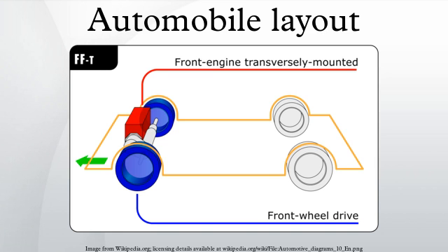Unusual 4WD layouts. From 1989 onwards, some models of Porsche 911 feature a rear-engine 4WD layout, which is akin to a longitudinal front-engine 4WD layout installed backwards with the engine at the rear of the car. From 2007 onwards, the Nissan GTR features a front-engine 4WD longitudinal layout, but with the gearbox at the rear of the vehicle. This provides a more ideal weight balance, and improves directional stability at very high speeds by increasing the vehicle's moment of inertia around the vertical axis. This layout necessitates a second prop shaft to carry power to the front wheels.